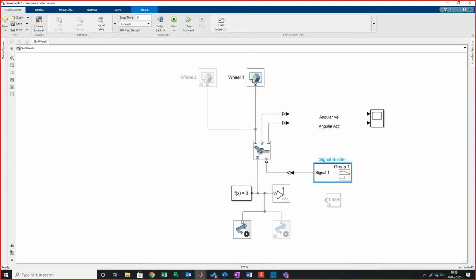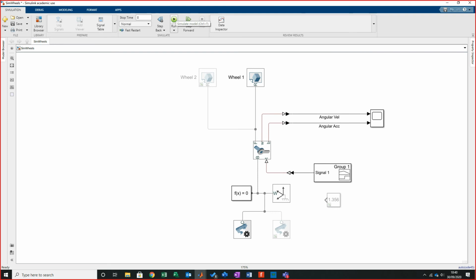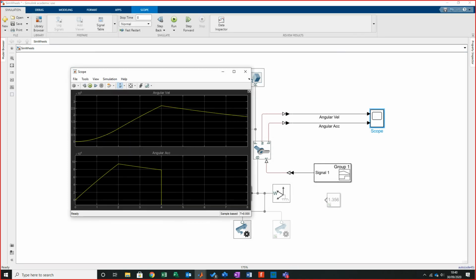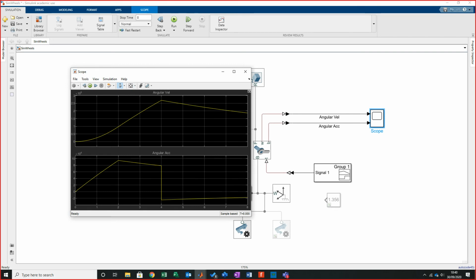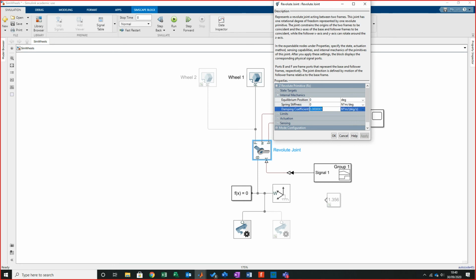If we wanted to look at what would happen if this started to become affected by the lubrication regime, we could go to inertial mechanics. We've still got that spring stiffness and damping coefficient. If I say on the damping coefficient that this has a damping of 0.0001, which ironically can give me some type of output for that lubrication relationship, and I run it again, what we end up with is a more skewed response. The second the acceleration drops off, it can't maintain it anymore and actually drops off, and in this case almost responds by returning on itself, because there's so much restriction in its motion. I can do all sorts with this, so I can implement that even more. Obviously if I make that bigger, it just cannot move.